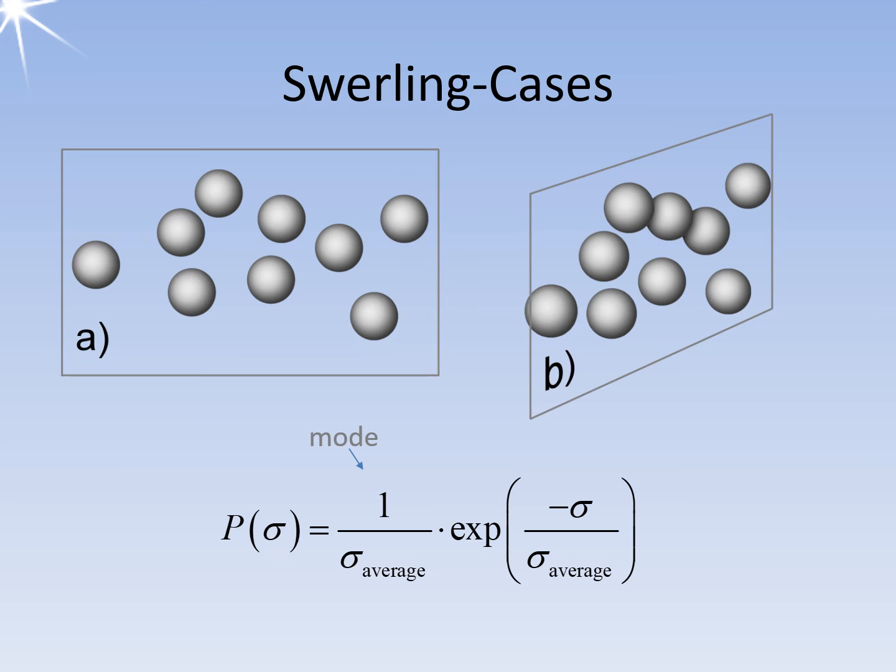It varies according to a chi-square probability density function with 2 degrees of freedom, m equals 1. The radar cross-section is constant from pulse to pulse but varies independently from scan to scan. The density of probability of the radar cross-section is given by the Rayleigh distribution.